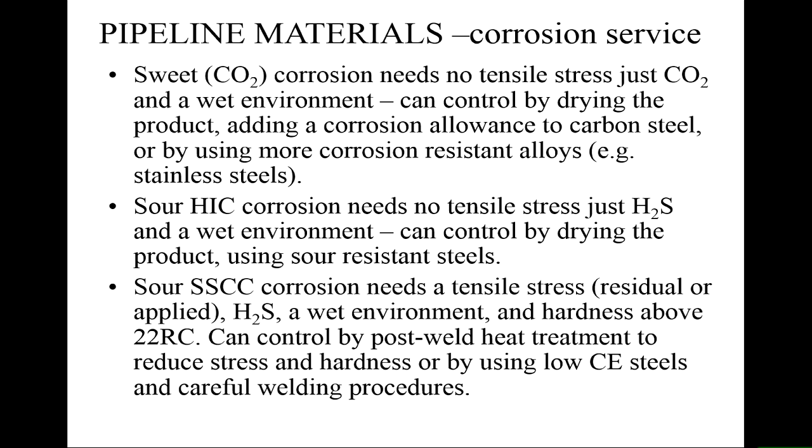Okay. So sweet CO2 corrosion needs no tensile stress, just carbon dioxide and water. And one of the easiest ways to control it is to dry out the product. That is possible, but very unlikely, because that adds to cost. So the next thing is to live with the corrosion.